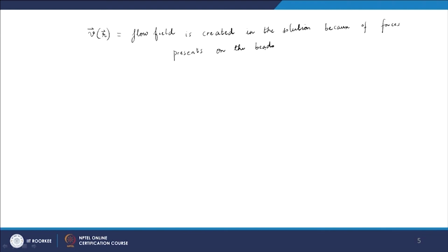Okay. So, we have to solve for the velocities, and we know from fluid mechanics that to solve for velocities we have to go to the Navier-Stokes equation. It turns out that since we are interested in motion close to equilibrium or motion at equilibrium, we don't really need to go to a large Reynolds number, because of course turbulent flow is far from equilibrium. We actually can go to a very low Reynolds number, and there we have what is known as the Stokes equation, and that is what can be used to get the flow field that we are interested in.